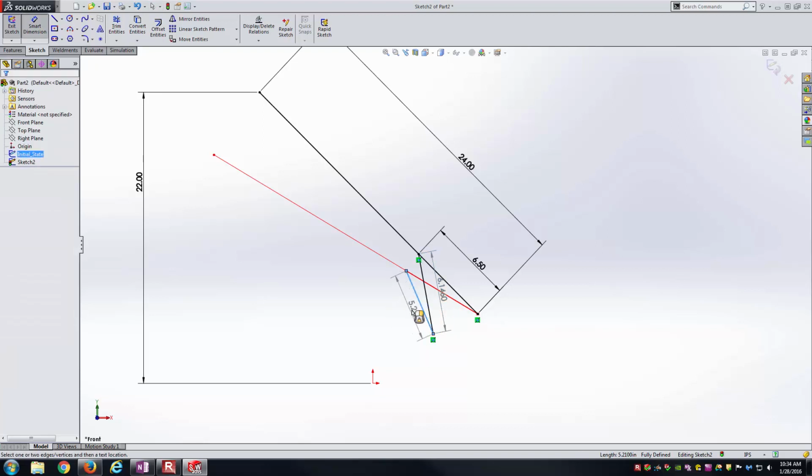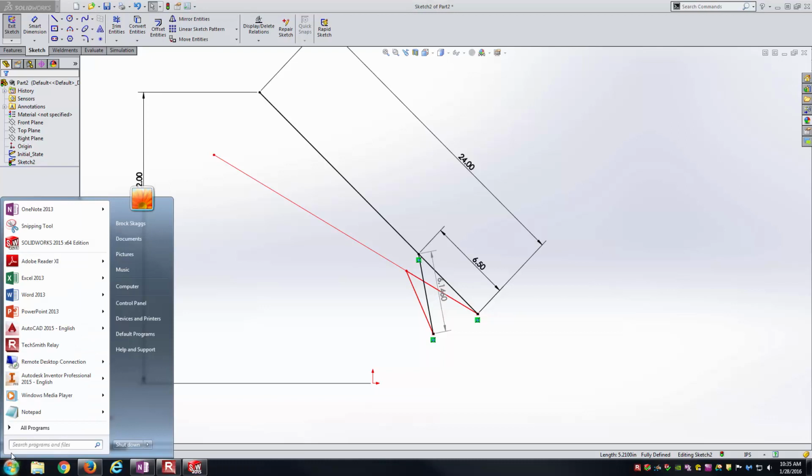I believe I can also, if I wanted to have reference, I can see there, I can't get it to show, there we go, that is 5.21 feet there. And so the difference in length would just be the difference of those two line lengths. And so I've got 6.146 feet minus the 5.21 feet from the previous one. I'm just doing that on my calculator right now. That gets me to 0.936, as far as the inches, or excuse me, as feet.